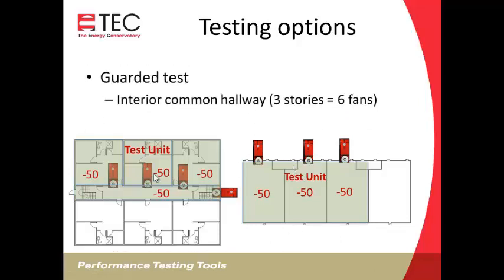Now this one is showing what's referred to as a guarded test, where any adjacent spaces, so any space that has an adjacent wall or an adjacent floor or an adjacent ceiling, are depressurized to 50 pascals.